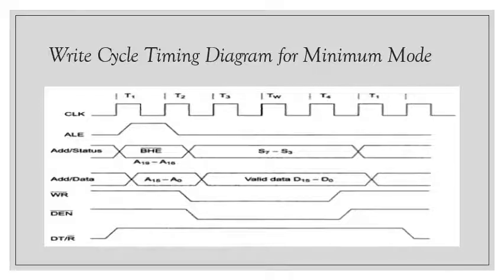A write cycle also begins with the assertion of ALE and the emission of the addresses. The memory or I/O signal is again asserted to indicate a memory or I/O operation. In T2, after sending the address in T1, the processor sends the data to be written to the addressed location. The data remains on the bus until the middle of the T4 state. The write becomes active at the beginning of T2. Unlike read, it is somewhat delayed in T2 to provide time for floating in the read cycle.